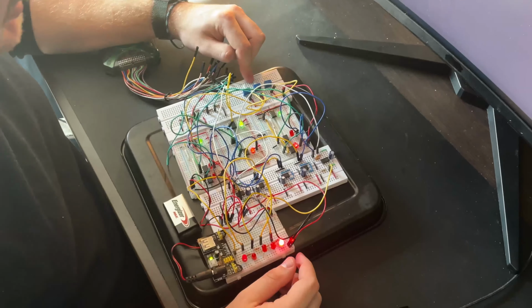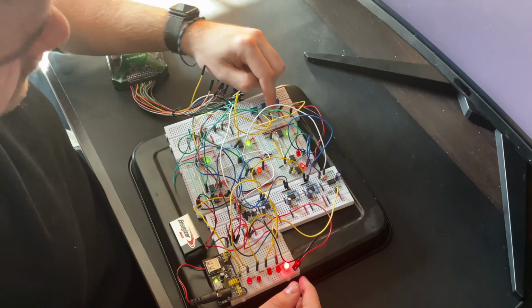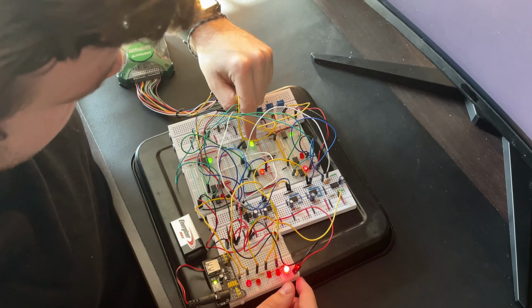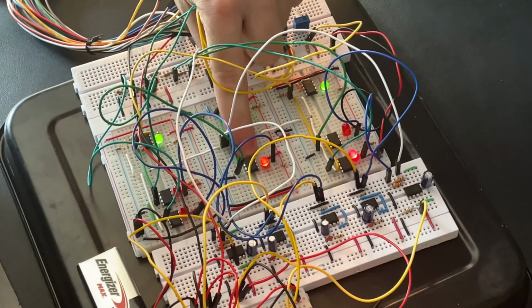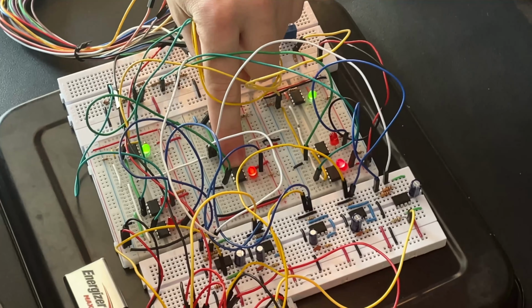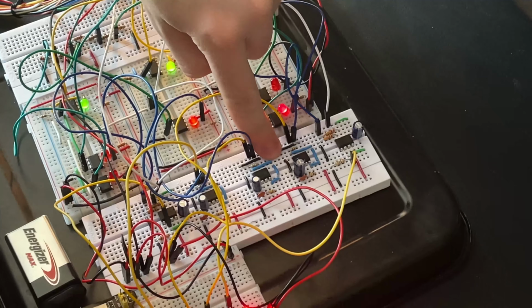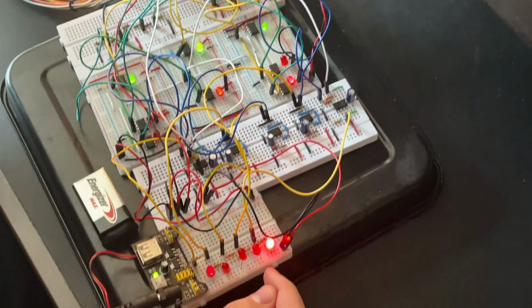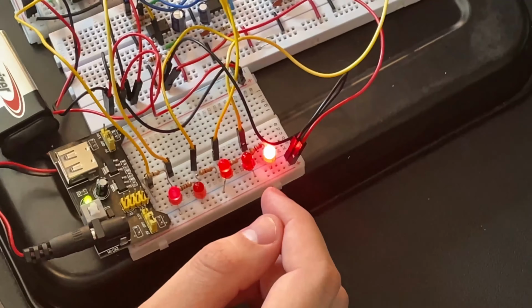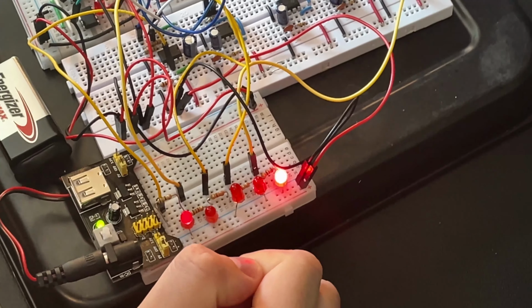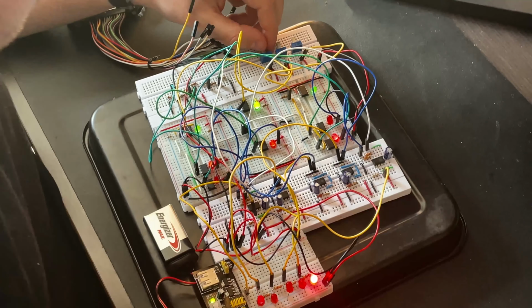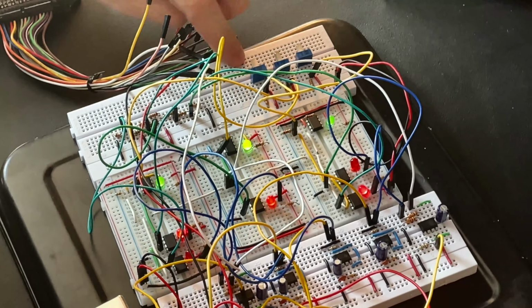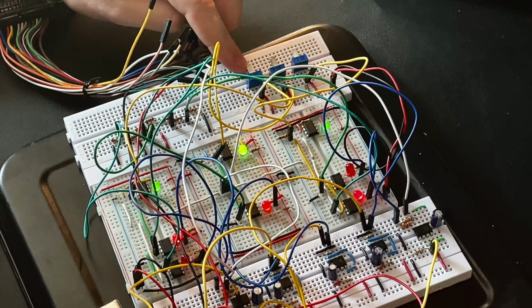Now taking a quick look at our CO2 sensor, we can follow it from here, goes to its amplifier for activity, then it goes to this comparator. CO2 only has a maximum we want to detect, so that means we only need to run it into a monostable multivibrator, and that one runs to this LED. Similarly to oxygen, we can turn it on and drop back to a safe threshold, and then it'll turn off after some time. Unlike milestone 1, O2 and pressure are now identical sans time constants.